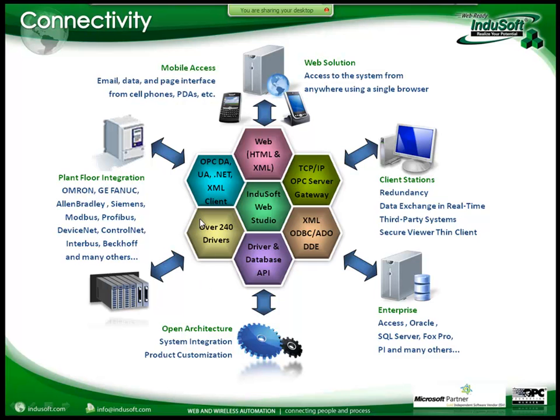And in addition to the drivers, we also install the OPC clients for all the major OPC specifications, including OPC-DA, XML, .NET, and OPC-UA. InduSoft was the first company to release an OPC-UA client, not only for PC platforms, but also for Windows CE.